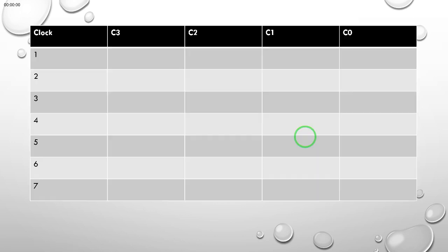So in that example that I have just drawn, we have started with 1, 0, 0, 0. We are doing the XOR combination, and whatever it is, these two are going to be the output. This XOR this is going to be the input to our C3. Then this is going to be 0, and everything else comes shifted by 1 bit.